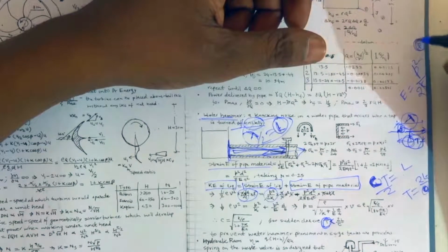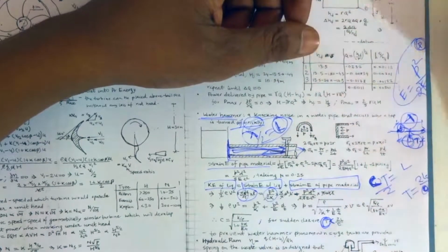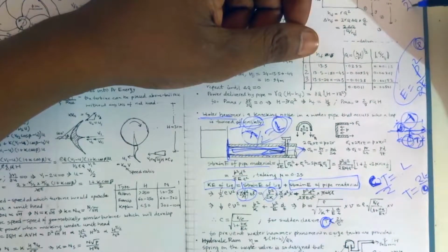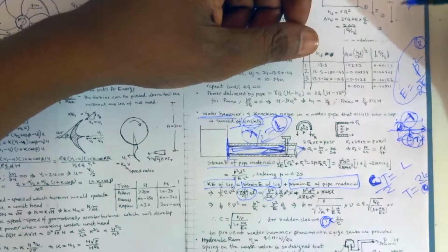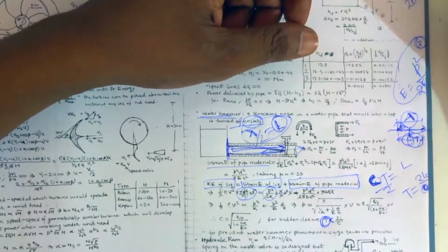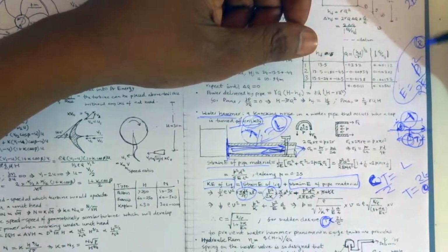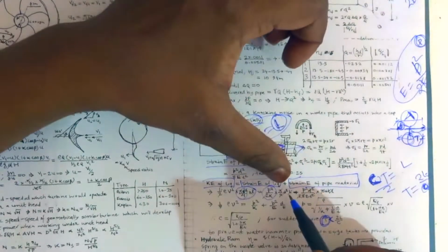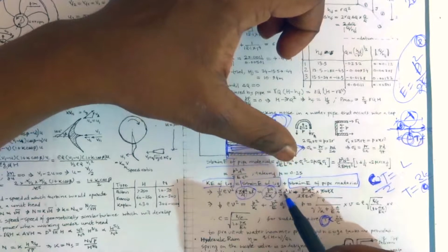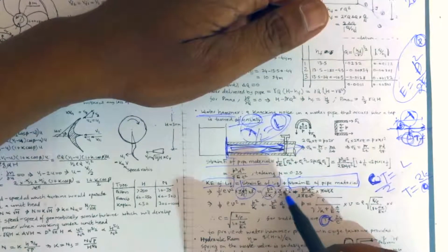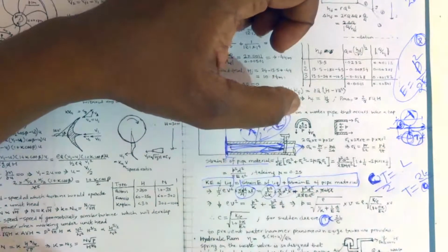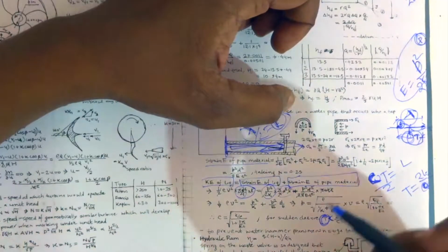This is similar to the case where M square over 2EI is the energy U; it is also dimensionally similar. So p square over 2k into the volume of the water, pi over 4 d square, is the strain energy of the liquid. Then the strain energy of the pipe material.